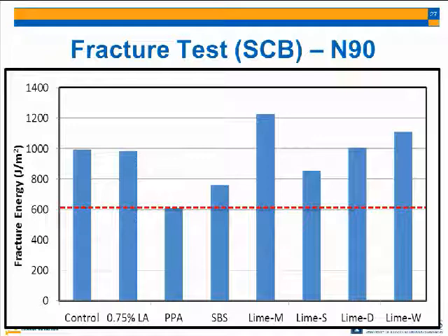The voids that you have in the asphalt concrete are completely different from what you have in Portland cement concrete, and they're usually larger. The stripping mechanism mostly happens when the moisture is inside the aggregate and tries to push the asphalt, or find a pinhole in the asphalt, and walk its way between the binder and the aggregate. But it's not because it is filling the voids in the mix itself, because usually you have a path for the water to move when it's freezing.